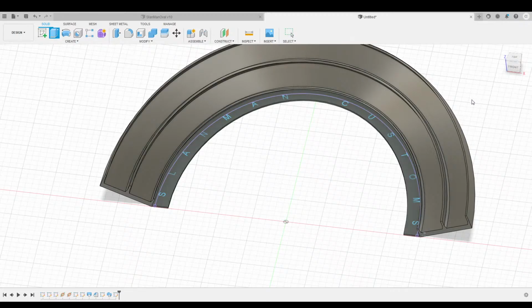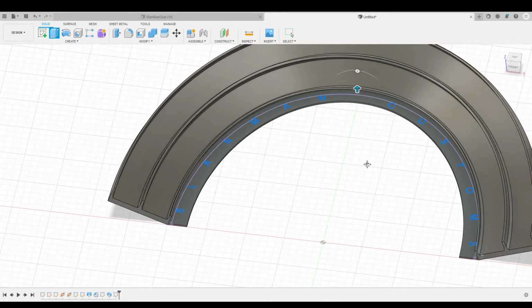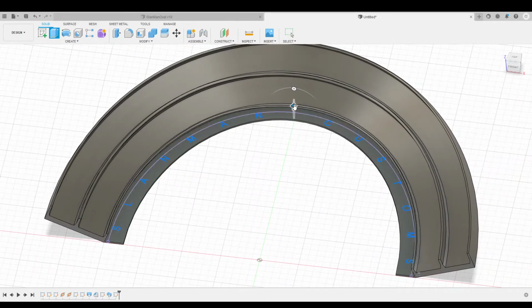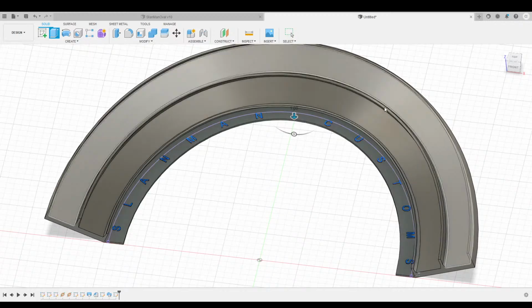So we're going to say we want to extrude it. And it automatically says pick a profile, so we're going to pick our text profile. And in this case, we have an arrow, whether it's up or down, so we want it to go down. But we don't want to go all the way through, because that'll make it kind of hard to print. We want to try to give us as much success as possible to print. So we know this is 2, so we're only going to go down 1 millimeter. That's going to cut in just 1 millimeter.